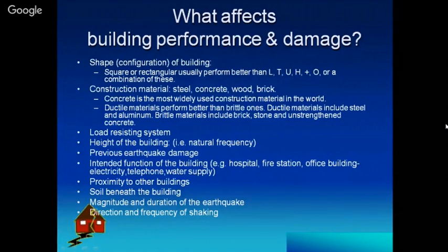Previous earthquake damage, if there is any in a building, first you are supposed to take care of that in the analysis part also, whatever type of analysis you are carrying out. Then the intended function of the building, whether it is a hospital, fire station, office building, electricity, telephone. Depending upon the importance of the building and the category in which it lies, you are going to plan the location and the forces of that building. Proximity to other buildings means the gaps you are supposed to maintain. It should not be too close.